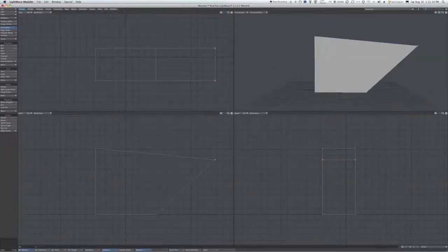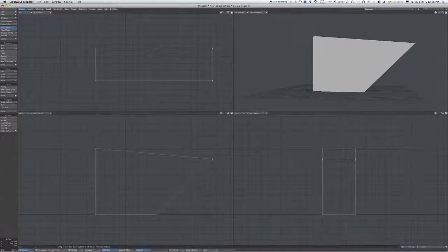As you can see, that's leaning over quite a ways. 45 degrees is where most support would automatically kick in if you've got it turned on. So if you make this slant more this way, so it's less than 45 degrees, most printers, at least a well-tuned printer, will print that.